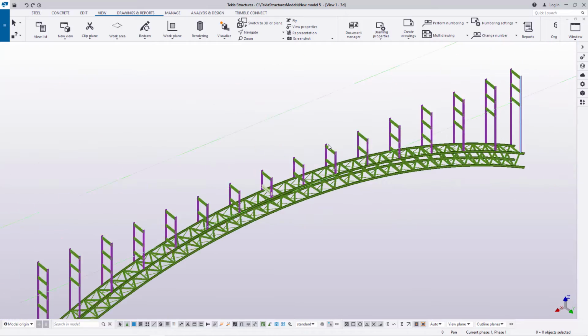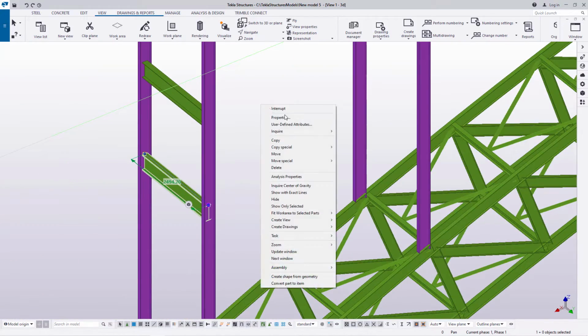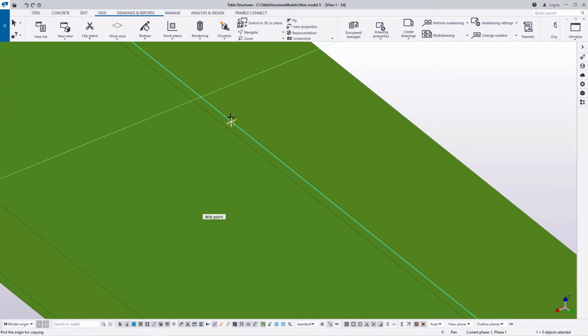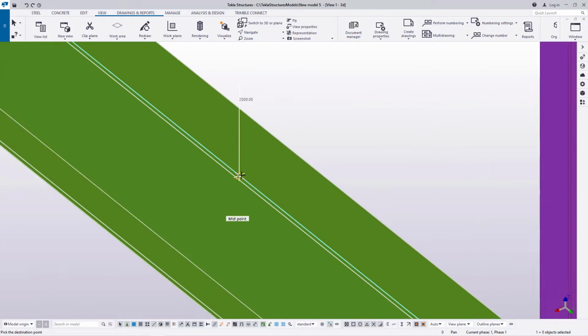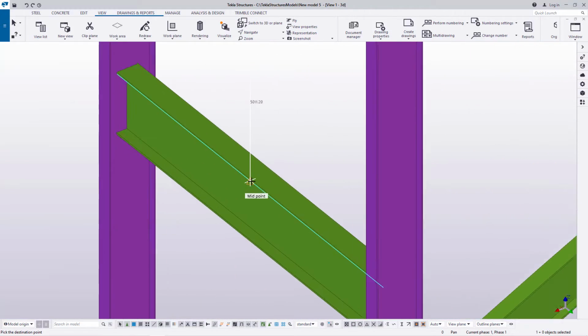So that's okay. Once you've done that, I'll come here again, right click and come to spatial copy. I'll snap on top here and pick it from that position and move all the way to the bottom end here, and snap on the same position to copy another one below it, and do the same thing here.